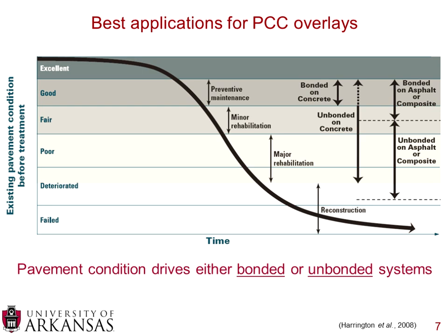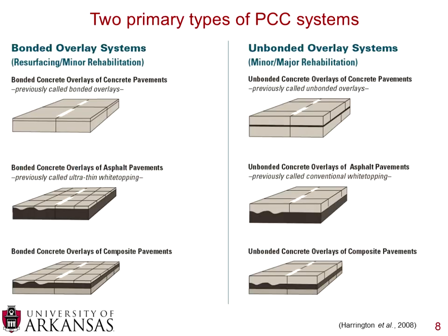However, as the condition of the pavement goes to fair and poor, they start going into the unbonded materials. So really, in order to get the full benefit of this bond, and we'll talk about bonded versus unbonded throughout the whole presentation, you really do need to have the existing pavement condition high, and then you're able to use that bonded technology.